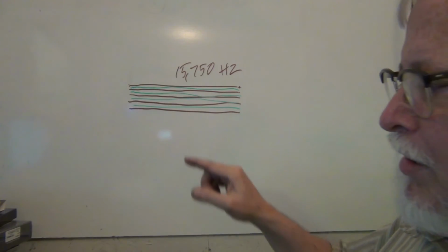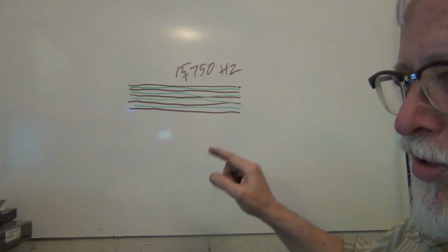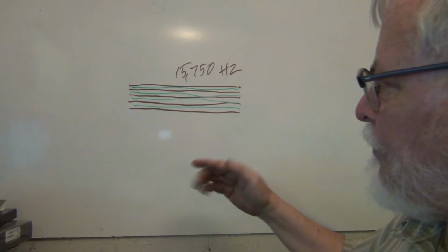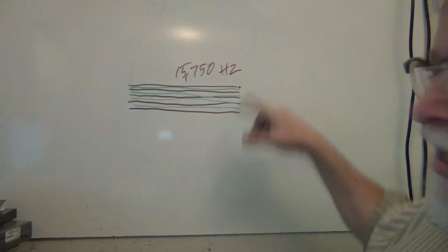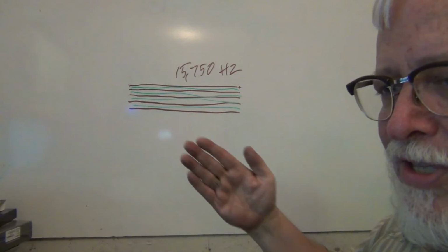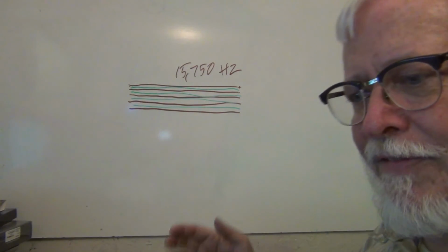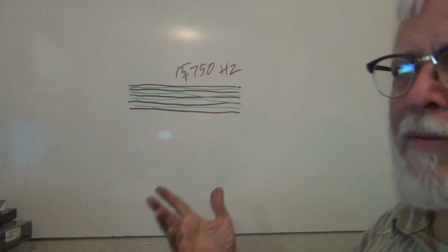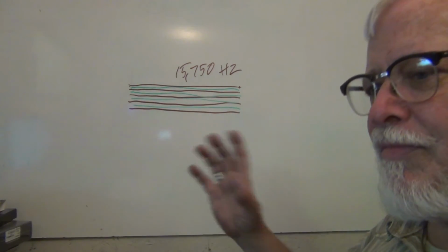Okay, in the Scanimate, you've got a horizontal sawtooth and a vertical sawtooth. So if you feed the horizontal one to the x-axis of the CRT and the slow one to the y-axis of the CRT, you get what looks like a square or 3x4 box. So then if you use the intensity of a video signal to turn that beam on and off, then you don't have just a square anymore. You've got the letter A or a picture of somebody's face or any number of things. So that's sort of the beginning.